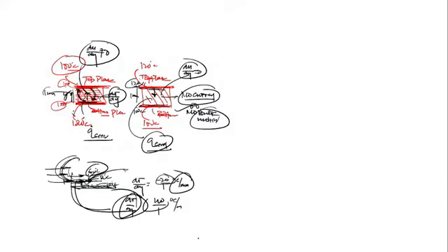When the fluid is in motion, it will sweep away the older fluid and a new low-temperature fluid will come. Due to this replacement, the new fluid will always be there, and that will increase the temperature gradient and hence increase the rate of heat transfer. Clear?